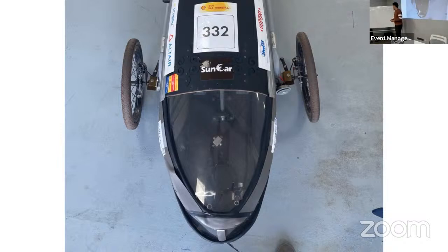Yeah, that's the right question. Because in hydraulic brakes, on the handle you have a reservoir which moves, so it compresses the liquid. And if you leave only one handle for 2 brakes, it will lose half of the power for each brake. It's going to work, yes, but not as it should. So our brakes may not work when we need them. So that's one, this is eliminated.